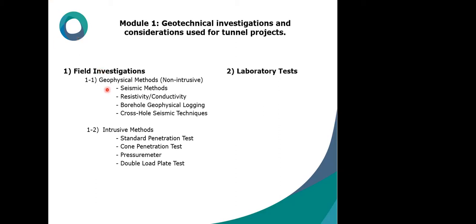So here we have geophysical methods, non-intrusive and intrusive methods. We divided them into categories: seismic method, resistivity, conductivity, borehole geophysical logging, cross-hole seismic techniques, and intrusive methods divided into standard penetration test, cone penetration test, pressuremeter, and double load plate test.